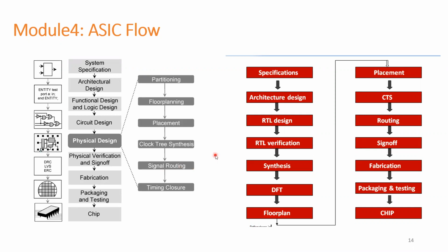All the physical shapes will be drawn at routing stage. So in signal routing stage, the track assignment and the signal routing, global routing, detail routing, everything will be done at signal routing. Once that is done, the tool will automatically optimize the signal DRCs. So there is an algorithm for that. This is an automated process starting from placement to routing. So you need to control the algorithm. What are all the strategies that you want to use, what are all the optimization techniques that you want to enable. So you need to control the tool basically to do the PNR process.